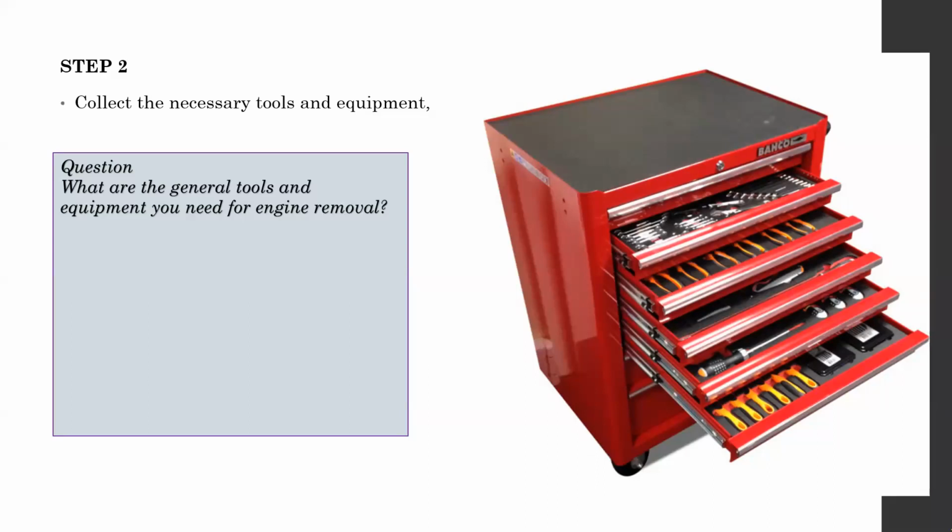Engine and gearbox assembly, if it is longer, then it's very difficult to tilt because the gearbox starts to rub against the floor. You can't turn more than that. In such cases, you need to lift the vehicle even a little bit, a few inches from the ground, in order to get the necessary clearance. So to get that necessary support, you need to have a jack, jack stands, or even a lift.